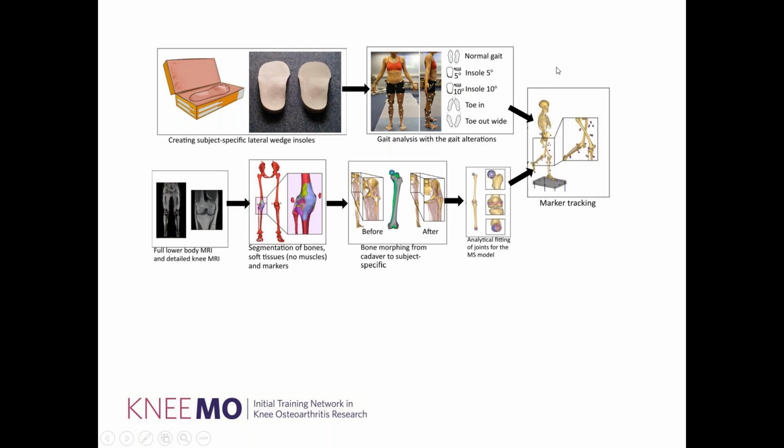Then we combined those two things, and then we did marker tracking. So we took our scaled musculoskeletal model, and then we got that to track the markers from the lab so that we have kinematics out of that. And then we want to use that for inverse dynamic simulations, where we take the measured ground reaction forces, apply them under the foot, and the movement from the kinematic analysis, and then use that to estimate the muscles and